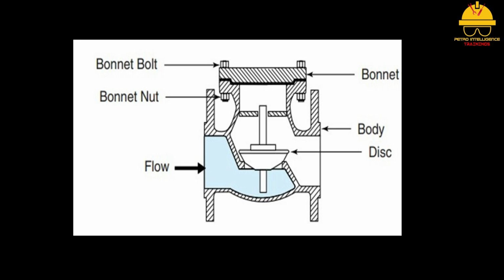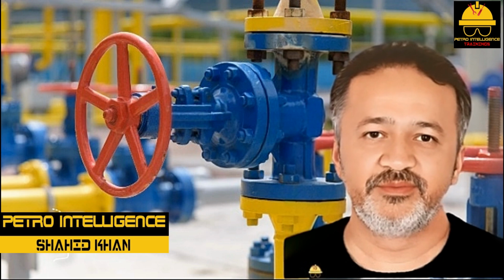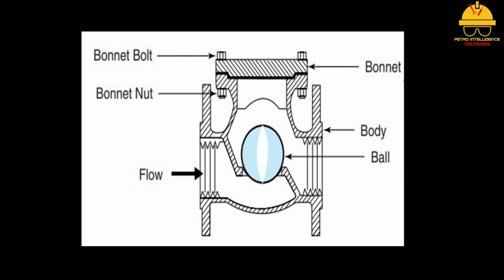In the horizontal or vertical lift check design, a piston or ball is lifted up and out of the seat by process flow. A third design is the ball check design, which has a ball-shaped disc that rests on a beveled, round seat as shown in picture. The ball is down when flow is idle and up when flow is active. Special guides keep the ball disc in place.